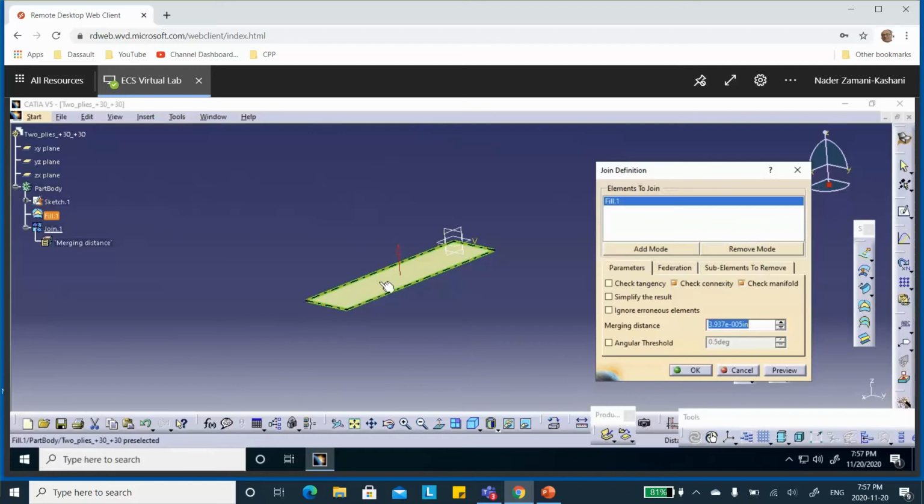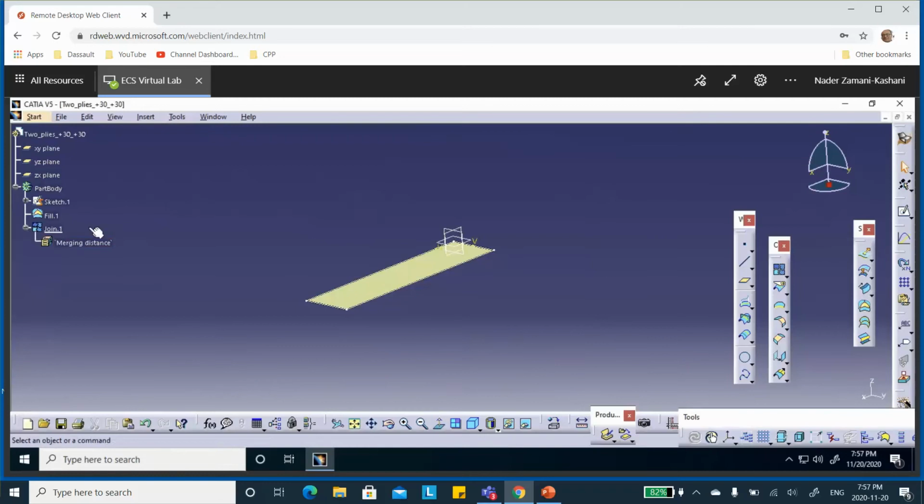Directions 1 and 2 are in the surface, and direction 3 is perpendicular to 1 and 2. Now, the direction 3 of the shell element is opposite of that. So if you insist on the direction 3 of the shell element to be up, for visual purposes perhaps, you flip this thing down so that the third direction is up. You say, okay.